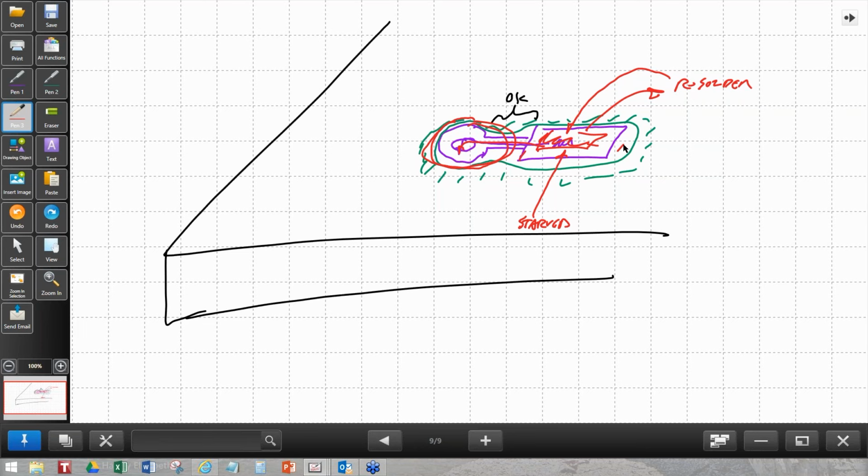You need to make sure that there's no through-hole type path. It doesn't matter whether this through-hole is a pad or a via. If its hole is open, you're going to have a problem. If it's a pad that's not soldered, if you have a DIP component going into a hole and you're doing wave soldering, the wave soldering will probably have been done and filled that up, hopefully first. If it wasn't first, then no, it won't.